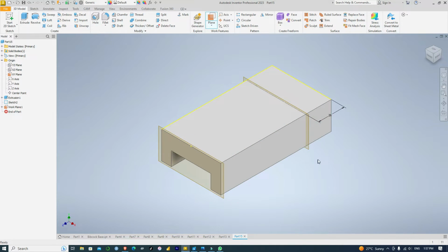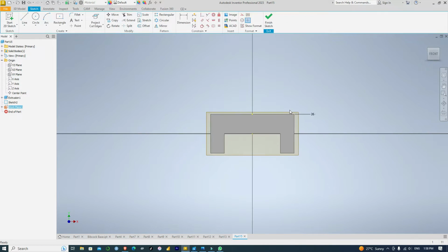then you click okay. Then what we do next, we're going to hide this, so the XY plane, no, this one, then you hide it, you make it invisible. Then this is the work plane, you're going to edit our sketch on this plane. So you click create sketch. When you create the sketch on the plane, what you're going to do is